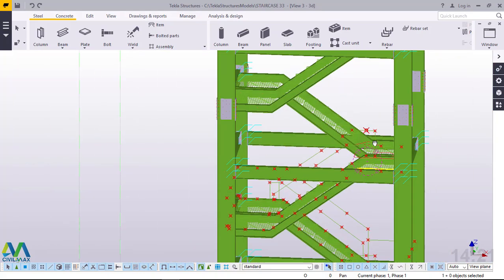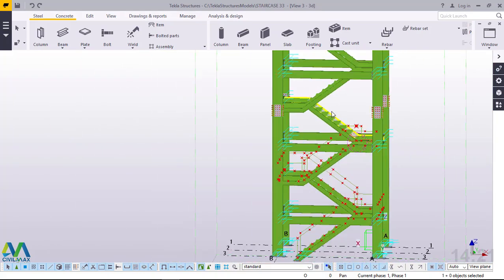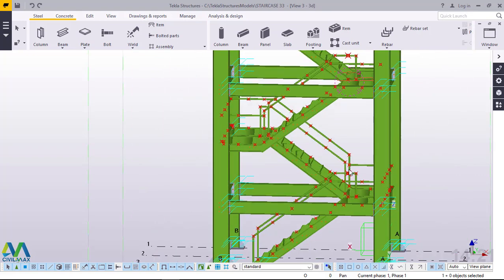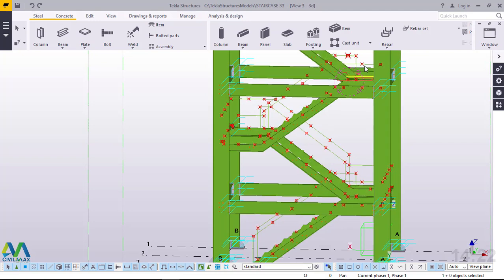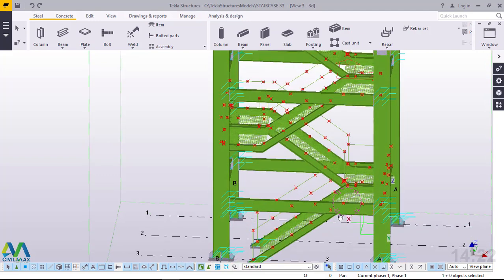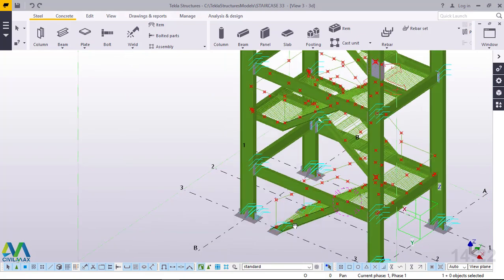So what we'll do, we'll not do everything up to the last height. What we'll do, we'll now place the posts for our handrails, and what I'll pick, I'll copy only this section. I'll select only this section and populate it to the full height of our staircase tower. Now let's do other things prior to getting to that stage.